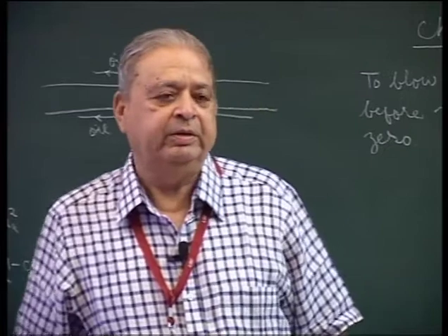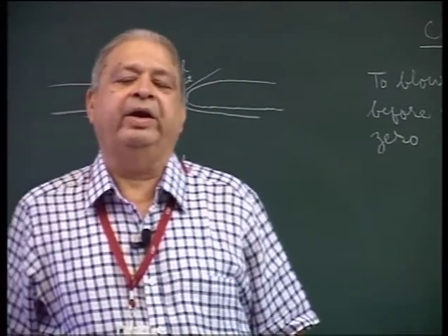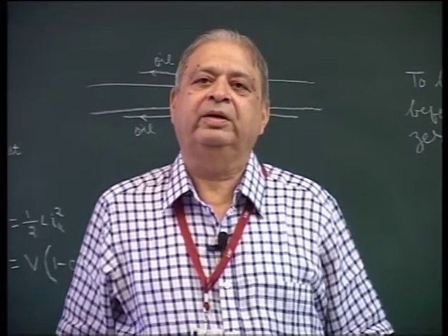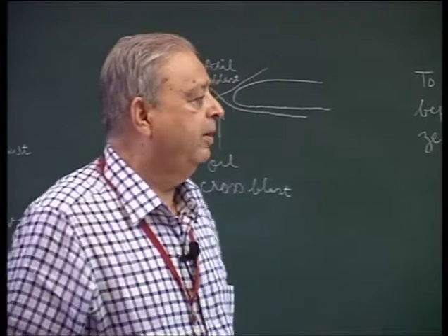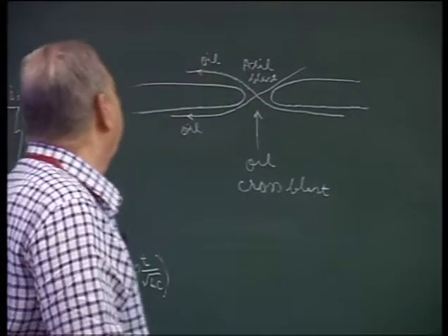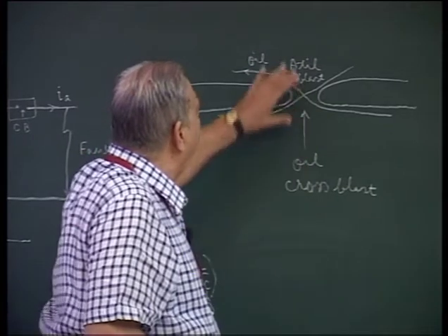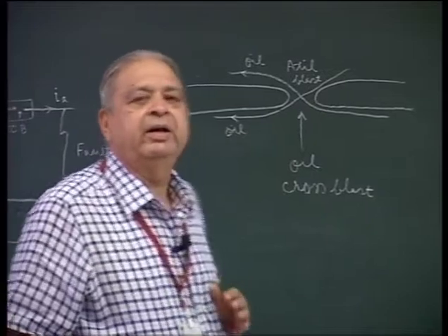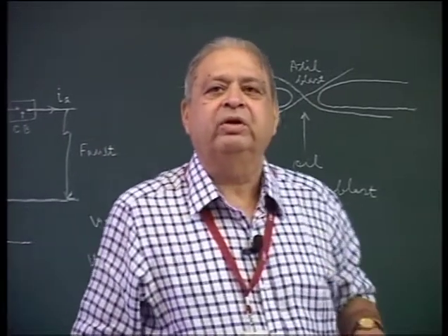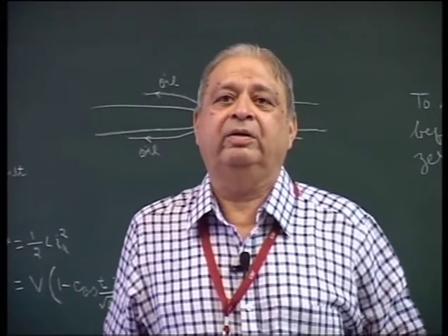Due to this reason, some circuit breakers are designed in such a manner that the arc is blown out by axial or radial, or a combination of axial and radial, force generated by the heat produced by the arc.